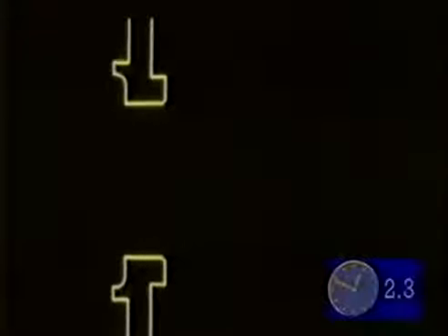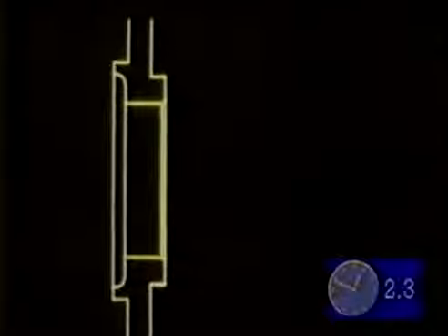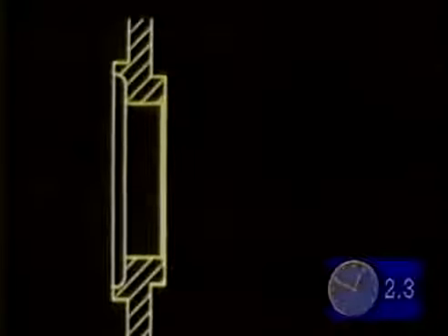Using a facility which allows features to be identified selectively, Alan isolates with the box those parts of the drawing which he would like cross-hatched. He must tell the system the angle of hatching required and the separation of the lines. The temporarily erased lines are then replaced, and on command the identified areas are hatched.